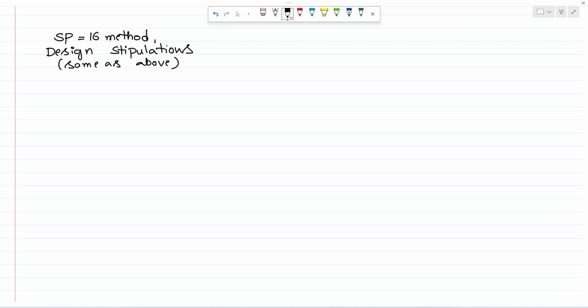Okay. So here first you calculate Mu divided by BD square value. So your Mu is the analysis moment. I think it is 130 into 10 power 6 Newton millimeter divided by your width of the section 200 into your effective depth.